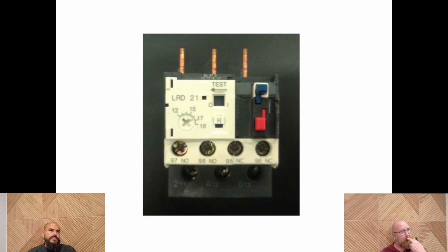It's important to understand they're less prevalent now than they used to be. But that's because we've started using VFDs, and VFDs kind of have a built-in overload relay in them. So VFDs will do a lot of the work to protect a motor that we were otherwise doing with circuit breakers and fuses and overload relays, because each of those was protecting the motor from a very specific thing.